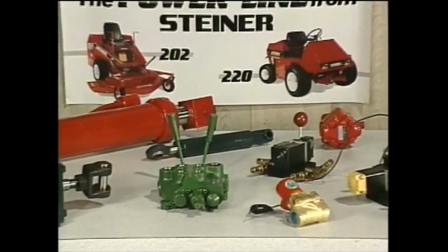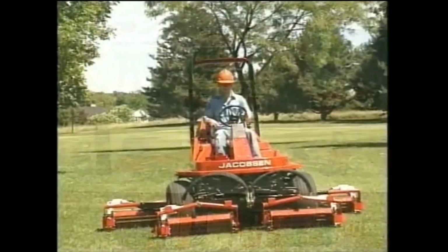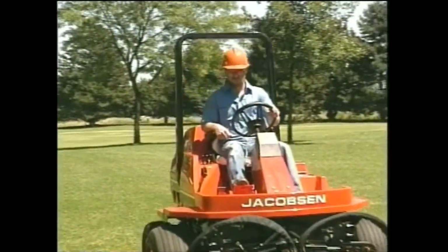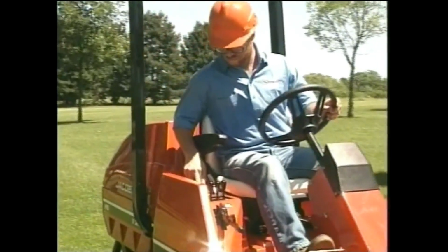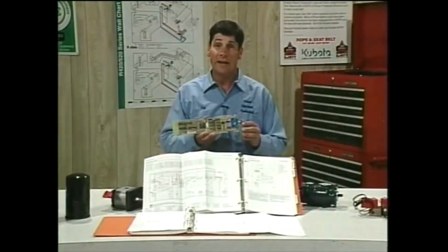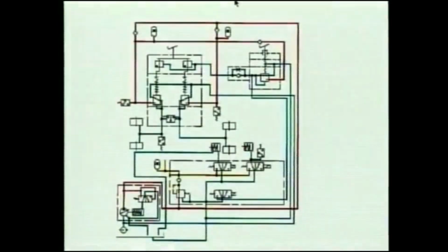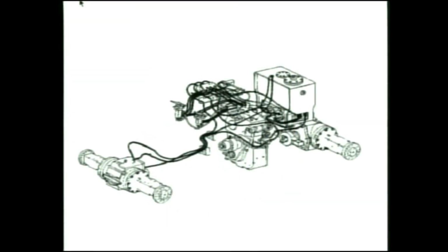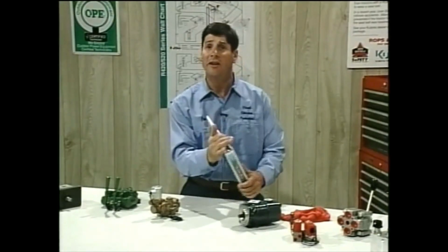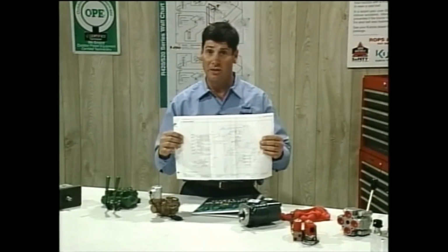The common components that make up a hydraulic system can look very different in size and shape from system to system. Because it is sometimes difficult to determine what function a component performs, it is helpful to have a diagram of the hydraulic system you are servicing. Just as electrical components are represented by symbols and circuit schematics, hydraulic circuits are also illustrated with symbols and schematic diagrams. Technical manuals expect the technician working on hydraulic systems to be able to read and understand hydraulic symbols and schematics.